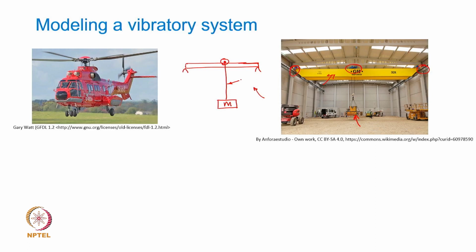So, if I assume the rope to have a stiffness given by a variable Kr, and if this girder is assumed like a simply supported beam, I can now treat the stiffness of this beam defined by a spring. Okay. The spring basically defines now the stiffness of the beam, and I will call this Kb.